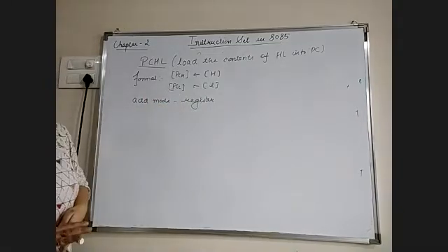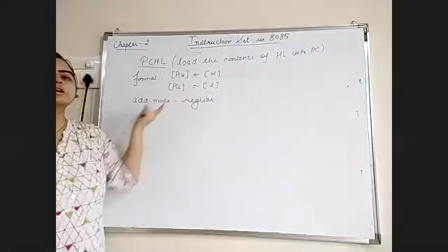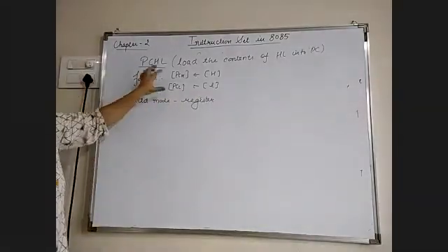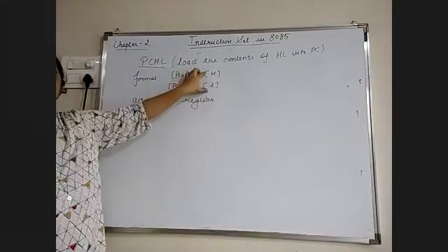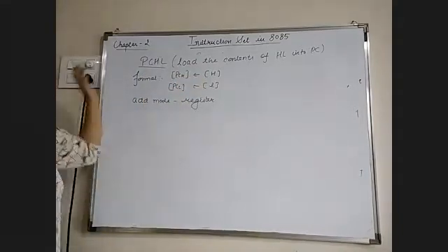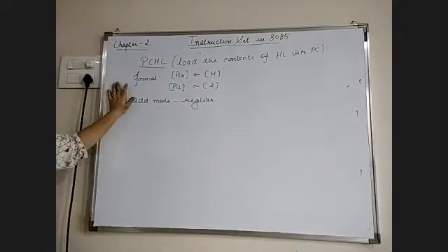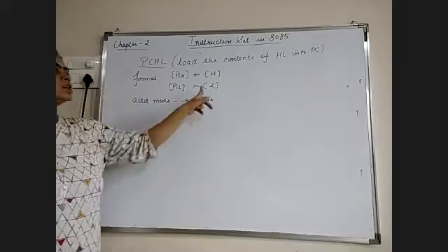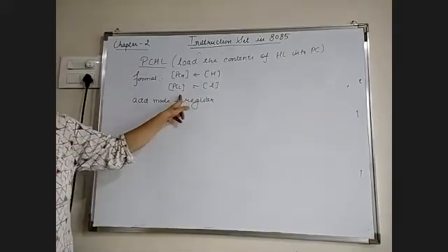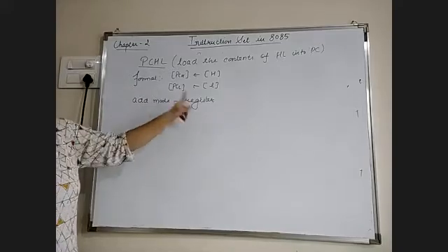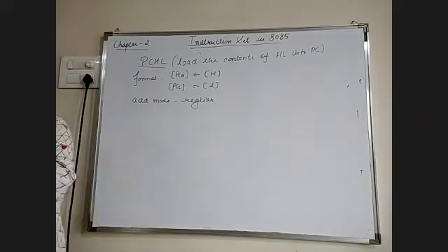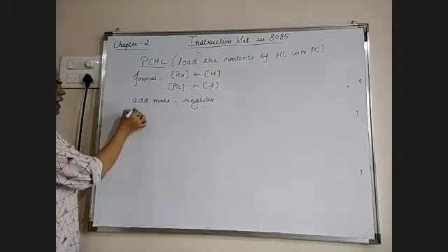Okay, so that means we are only dealing with 2 different types of register. One is the special purpose register and the second one is the general purpose register. So this instruction means to load the contents from the general purpose register to the special purpose register. So that means the addressing mode is the register addressing mode, because both the source as well as the destination are registers only. Okay, next, after addressing mode, flags affected.